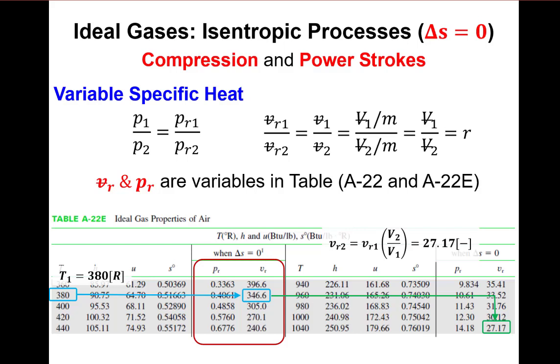So here, that means it has to be adiabatic, right? The heat transfer has to be 0. Otherwise, if I did the second law here, I would have sigma, the entropy generation rate, to be 0, but that wouldn't make delta S 0, right? So this only works when it's work being solved for.